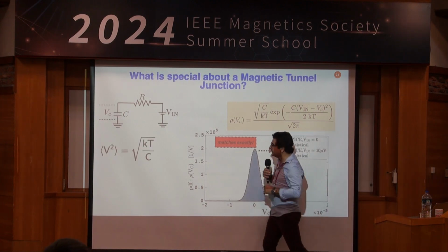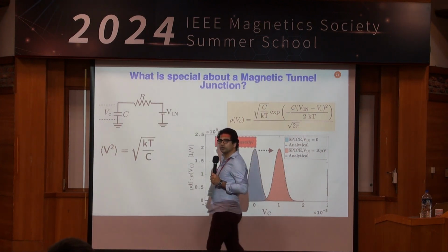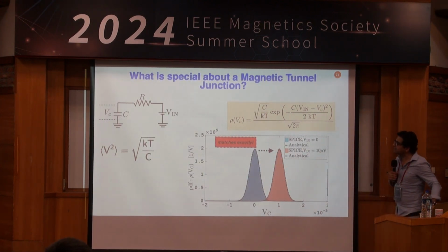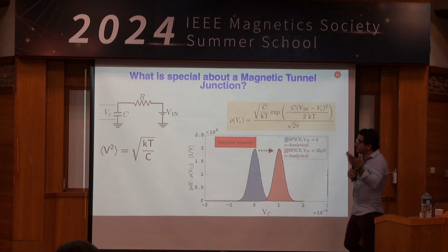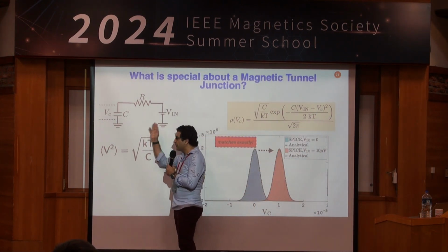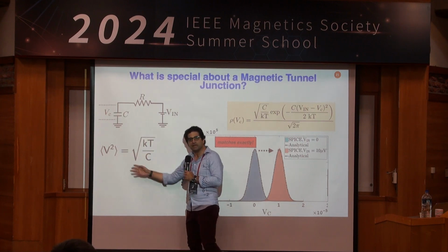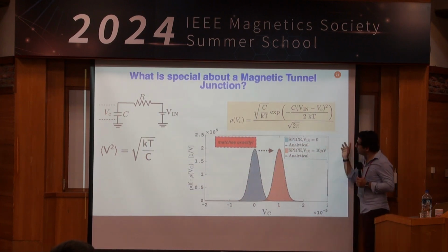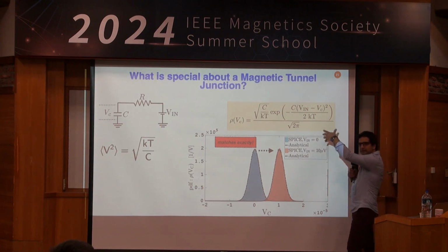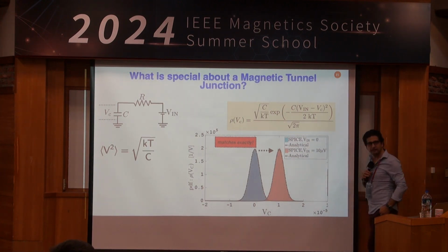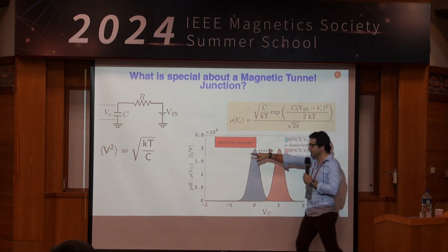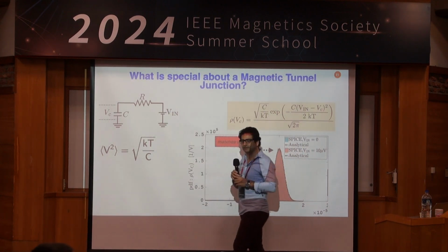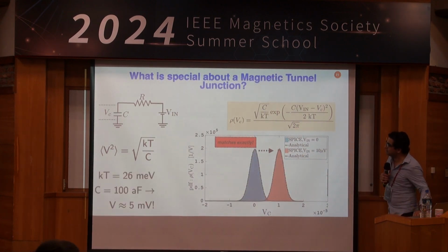So it looks like the RMS, or the squared mean fluctuation on that resistance or capacitance, is going to be the square root of kT over C. That's a beautiful result, and you could study the equipartition, things like that. You could probably get to this result in a less rigorous way. But other than integrals that you don't have to take, I find this very instructive. This is a better way to write that wiki page. It's not written like this. You'll see this, but it'll come from some complicated thing, okay? So that's V squared. So let's do some math here.